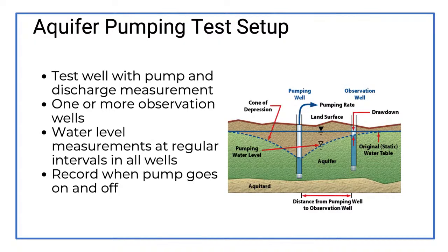This is kind of our setup. We're going to have a test well with the pump, and we're going to measure. We need to measure our drawdown. We need to measure our pumping rate. Those are the two parameters that are important to measure.